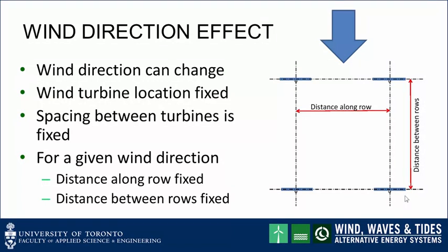We know, however, that the wind direction can change. Our simple four wind turbine layout wind farm can illustrate this. So here are our 4 wind turbines, and suppose that the spacing between turbines was chosen for the wind direction shown. So we essentially have wind coming from the north. For example, let's suppose that the distance along rows was 3D as from the table previously and 7D downstream, and then we know this would give a very good performance, array efficiency of 93% with a very compact layout.